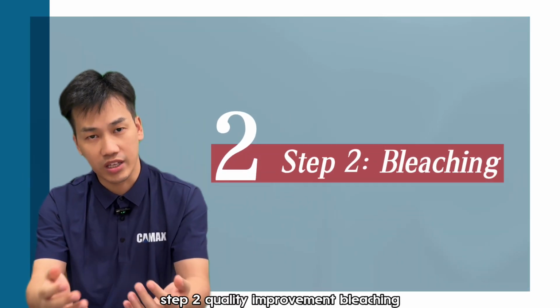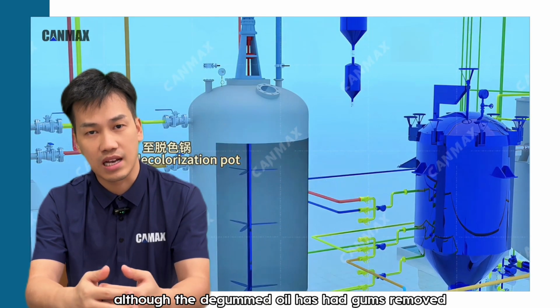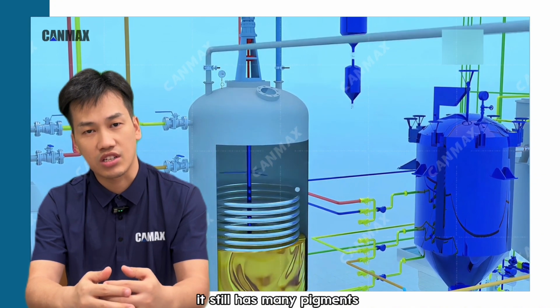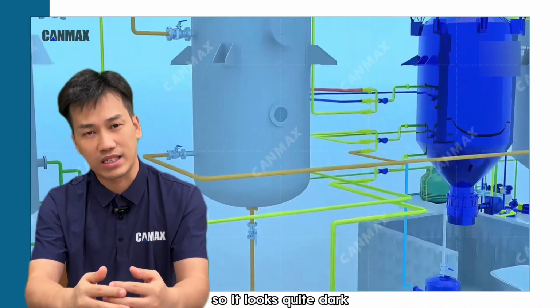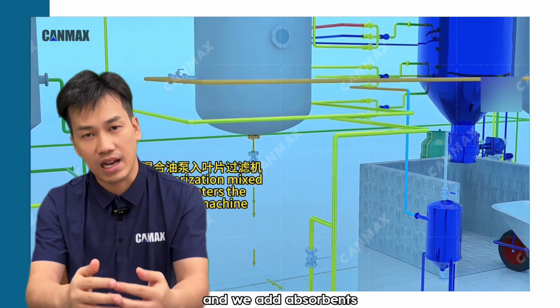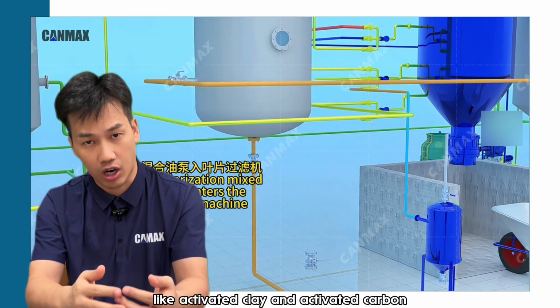Step 2. Quality improvement. Bleaching. Although the degummed oil has had gums removed, it still has many pigments, such as carotene and chlorophyll, so it looks quite dark. That's when it enters the bleaching tank. And we add absorbents like activated clay and activated carbon.